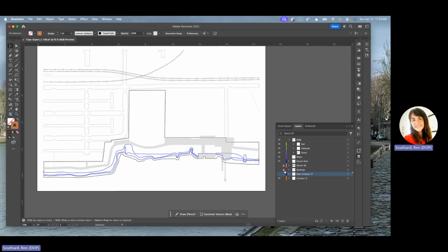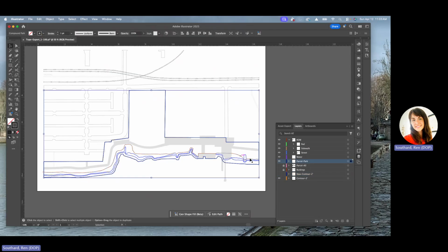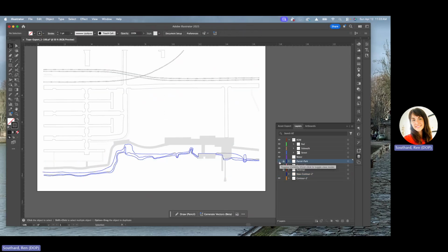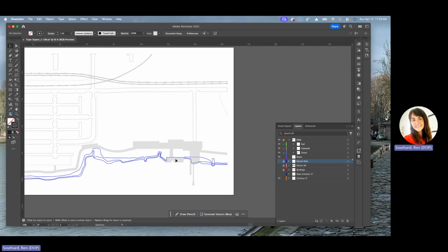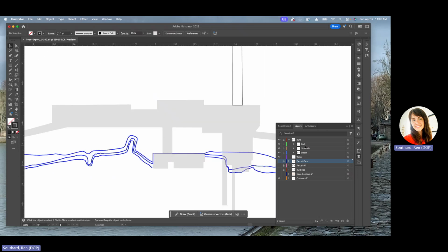I also don't need my parcel right now. This is the park parcel here. And we've already got that, so I'm going to turn that off. What I do want is for the right of way, which I've made this sidewalk slightly lighter. I've made it an opacity. I think I did it at 50%. Yeah, 50% up here. And that's because I wanted to be able to see the topography lines as they run underneath. And this right here is a dock.